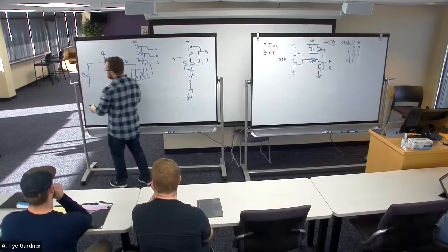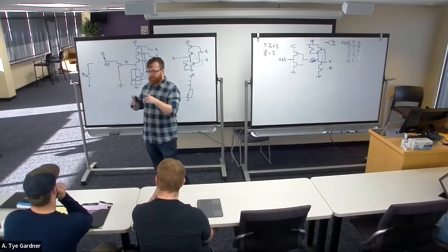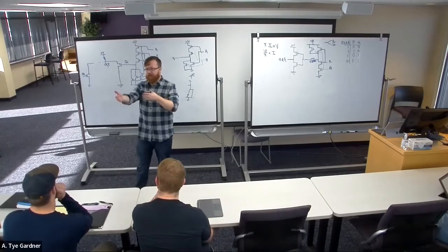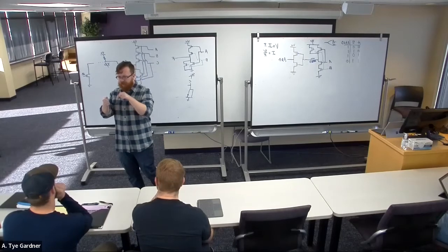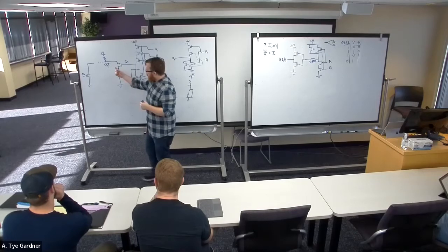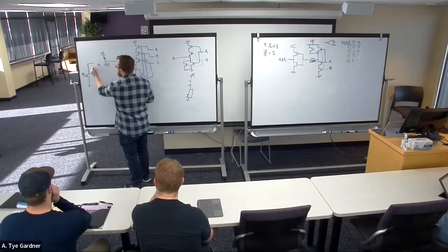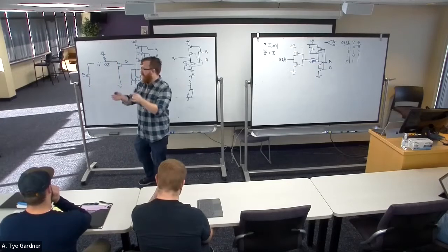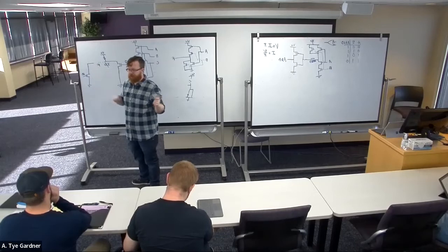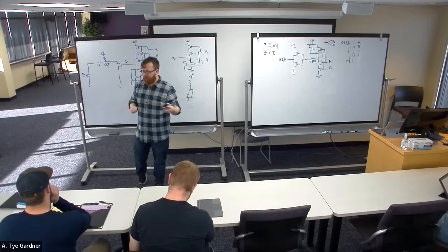And let's say I build a digital logic. Let's call it an FPGA. If we're going to learn how to build FPGAs, let's say I build one and you build one, and they want to talk, and we only have 2 wires. Well, one of them we're going to share the ground, so we know that the reference is the same. And then we're going to connect this wire. I haven't used F yet. Together, they're plugged together, and one side or the other or both may have pull-up resistors. It doesn't actually turn out to matter very much. Most of the time, it'll be only 1, but it's okay if it's 2.